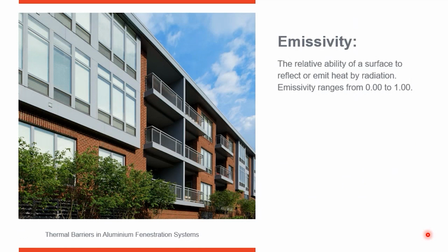And then as far as radiation, here's a nice photograph of a dormitory, and you can see all the windows. So great use of windows there for daylighting and views. But if you notice, the blinds or the shades all appear to be closed. And this is a morning photograph, so most likely we're getting direct sunlight through these windows. That's bringing heat in, and the occupants on the other side have closed their blinds to cut down on the heat coming through. So this glass probably does not have a low E coating on it.